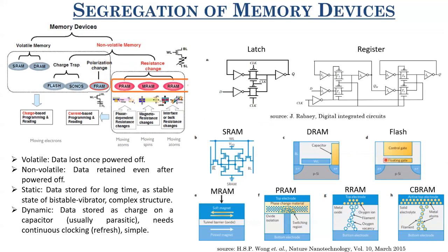So what happens exactly is these ferroelectric materials are non-centrosymmetric. What I mean by non-centrosymmetric is, in your symmetric structures or in your symmetric molecules or symmetric crystalline structures, effective polarization is zero. Net polarization is zero. There would be some dipoles, but the dipoles pointing up and pointing down will kind of cancel out each other, and overall polarization would be zero.